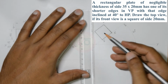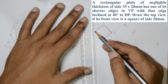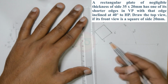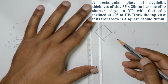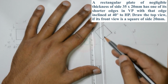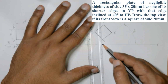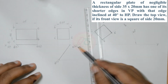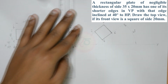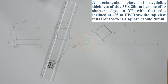From C dash, draw the projection line. Similarly, from D dash, draw the projection line. From B dash till the XY line, since AB is lying on the XY line, and A dash till the XY line, so that the edge AB will always be in touch with VP.